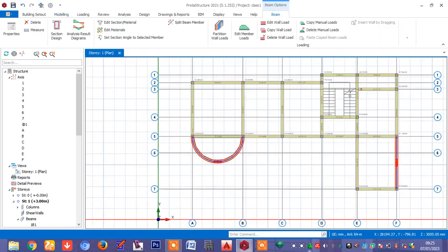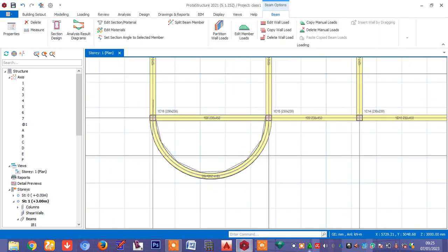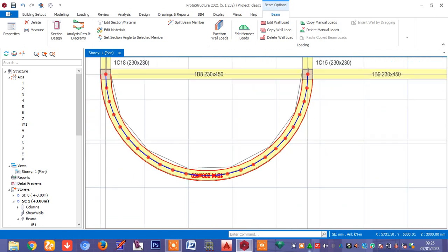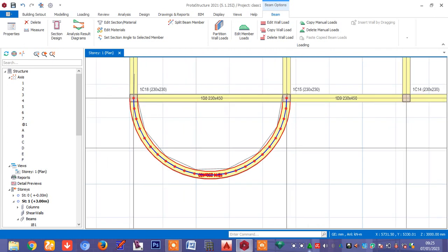But if you look at this very beam now, the span here, it's actually long, should be up to, let me say, 7 meters. So you know that a beam of 450 cannot stand the span there. So based on the code, based on experience in design, I can decide to use a beam of 600.